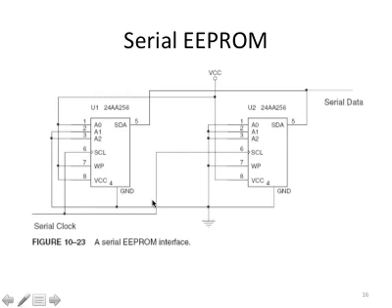So there should be another 15 pins on the chip. Well, not 15 pins, because the chip will take those 15 address bits through the same wire, because this is the only wire you can use to talk to the chip. This is SDA, the serial connection. So all these address bits come through this pin into this chip to select a location within that chip.